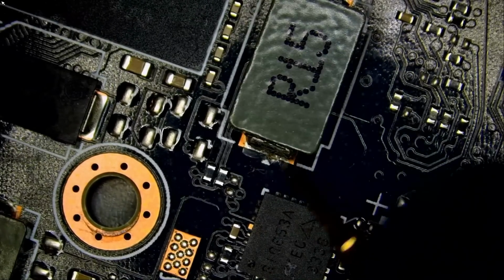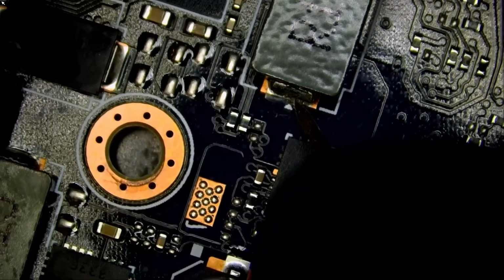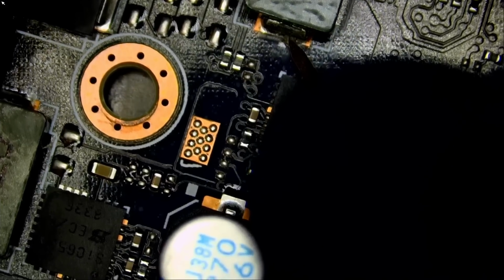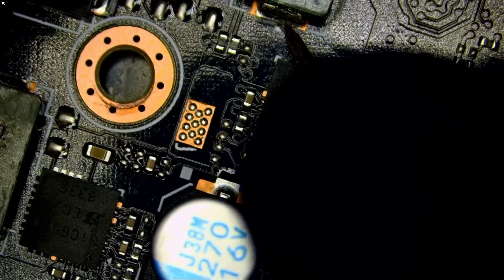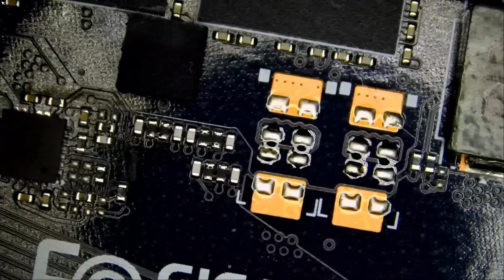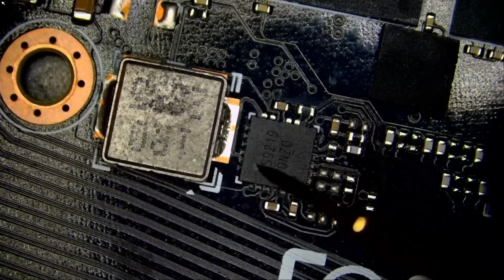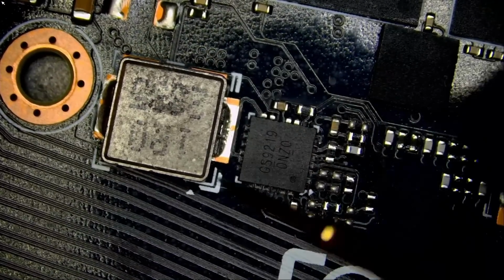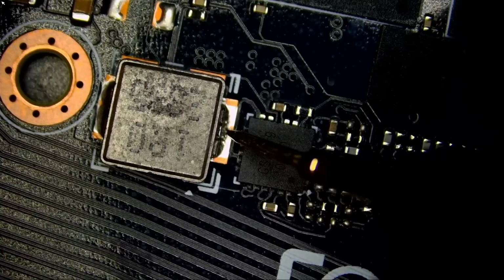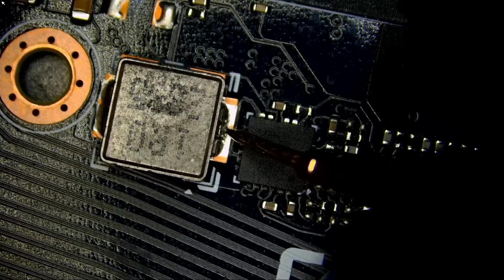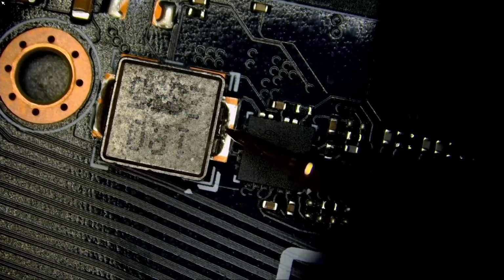If we measure in resistance mode, memory, 79 ohms. Let's measure our 1.8 volts. This should be our 1.8 volt line here. Let me measure in ohms mode. We should have something like 227. I'm reading 251 ohms. That's good. Close enough.